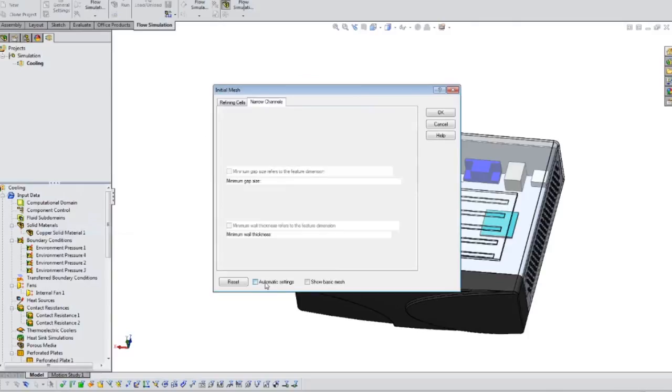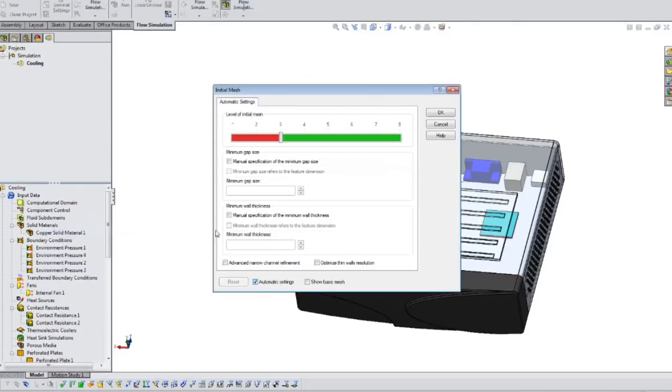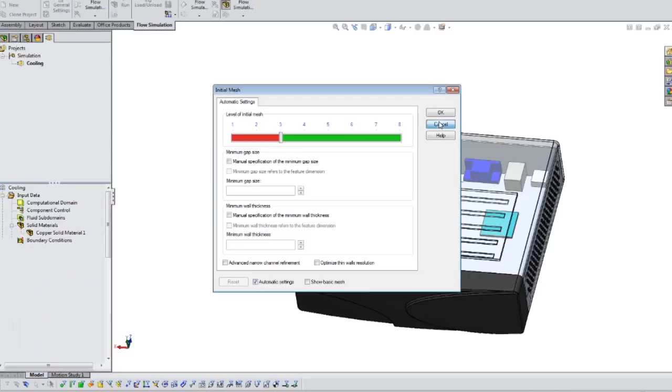We know that a PCB has orthotropic material properties. The material properties through the board are different than across the board. What the PCB Generator allows you to do is plug in all the layers for your PCB and the percentage of copper covering, and then it calculates those material properties for you. Certainly you could do that on your own, but the PCB Generator really makes it easy for you.